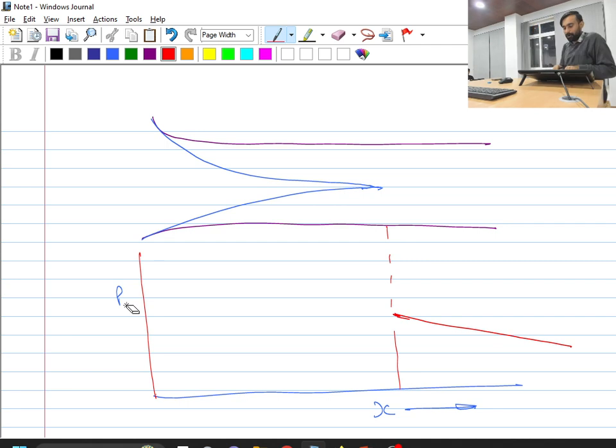Okay, so if wall shear stress is constant, and pressure drop is majorly caused by the wall shear stress, which we will see in the subsequent discussion, and what we are doing after this point is only increasing the length, so the viscous effect is constant, but length we are increasing linearly. That's why pressure will form a straight line.